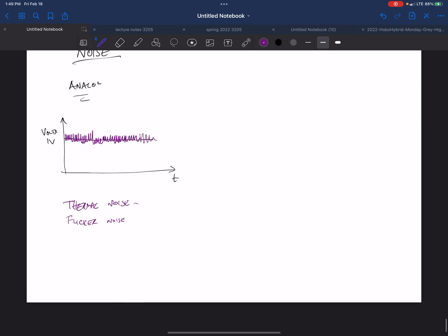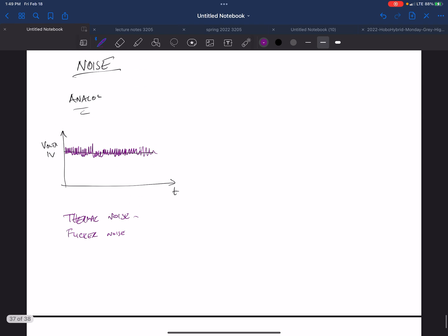This by itself already sets some lower limit to your noise. So just think of the thermal noise, okay? Have you guys done probability distribution functions, probability theory, Gaussian probability distribution? White noise is Gaussian, so it's a little easier to do. If I draw the amplitude distribution of this, you'll see something like this. This is the distribution.